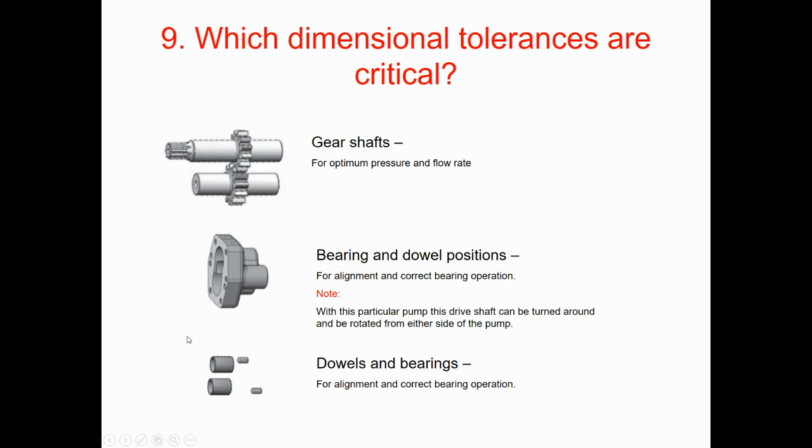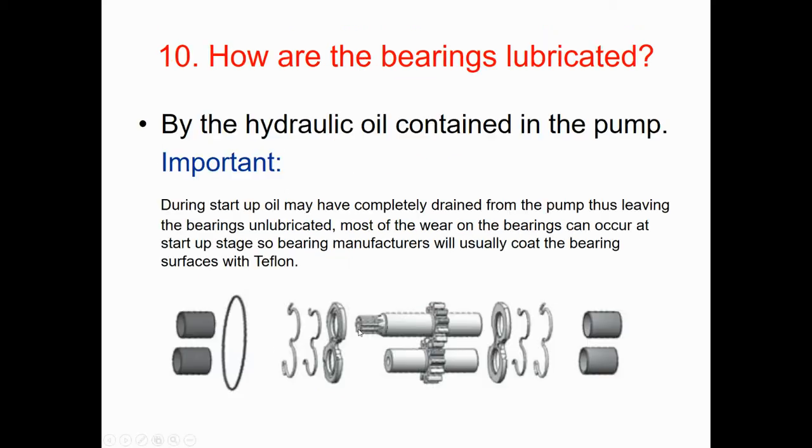And we're going to talk, actually, we talked about the process of how to achieve very high dimensional tolerance for the holes by doing the drilling, the boring, and then we need to do the reaming. So we are going to achieve the exact dimension we are after.